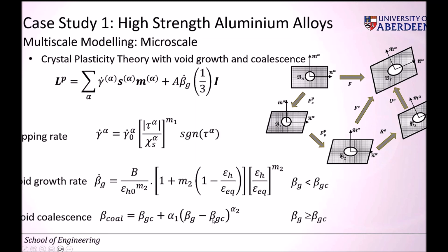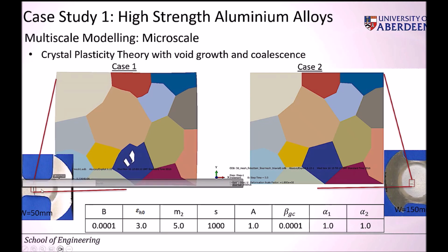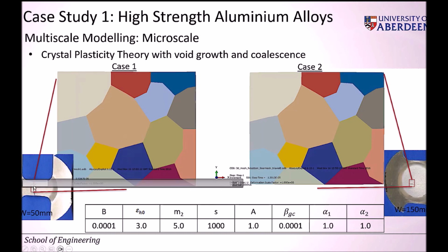And we incorporate those in complex models. We implement these in UMATs, the material subroutines of Abaqus. So we interface our code with Abaqus, and then we run the simulation. This is one of the simulations taken from this area of the microstructure, and you can see in this case the failure was occurring in this direction, so we were able to predict that.